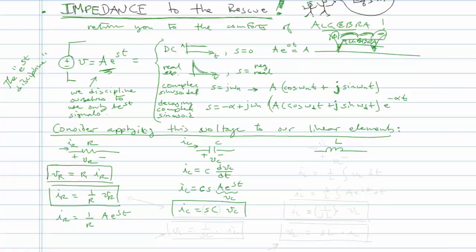This is very interesting, because if you compare it to the resistance, we see that in fact we have what we were hoping for, that the current is truly just a constant away from the capacitor voltage, or vice versa. So we could write the capacitor voltage Vc is equal to 1 over sC times Ic.